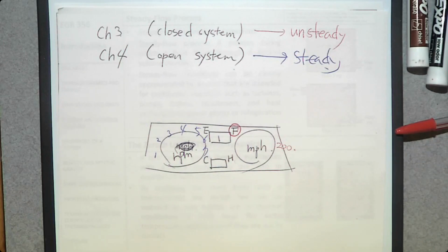However, this is the most important gauge, because you usually see at the beginning, when you just start your engine, it is pointing at C, right? It means that the engine has no heat inside. While you are running, we call it warming up, right? While it is warming up, this gauge goes up. What does it mean thermodynamically? Unsteady process. And after 5 to 10 minutes, you see it pointing right at the center. That means steady state. So when you're driving your car to come to the campus, initially your car is in an unsteady process and becomes a steady process.